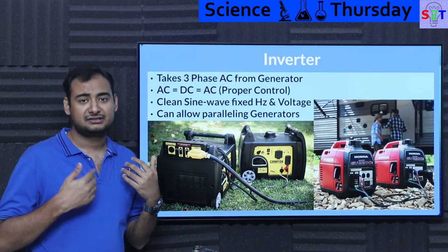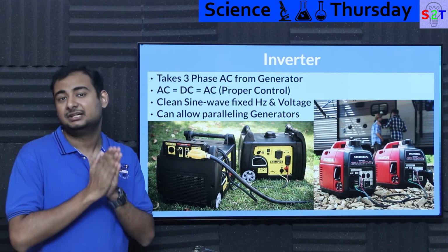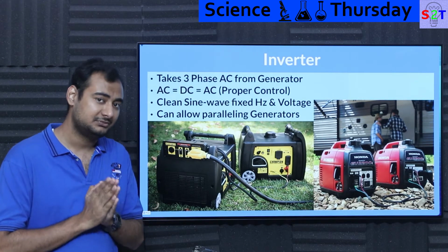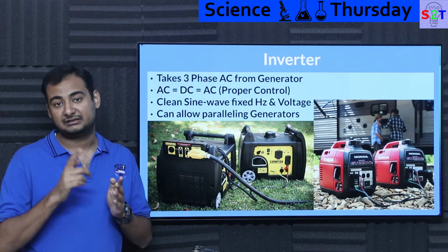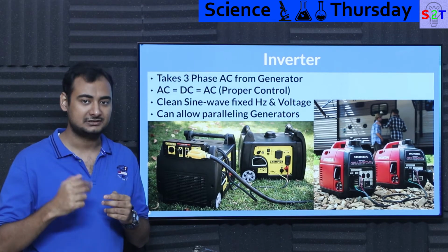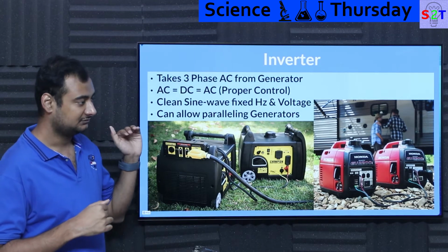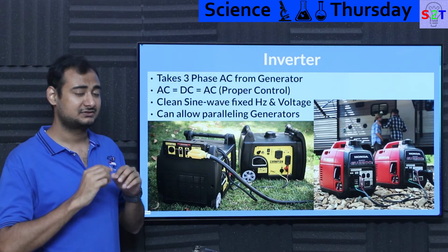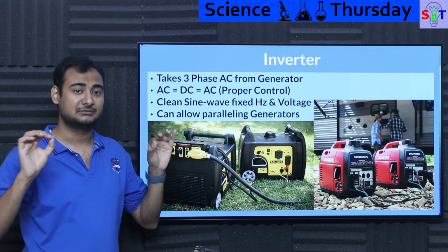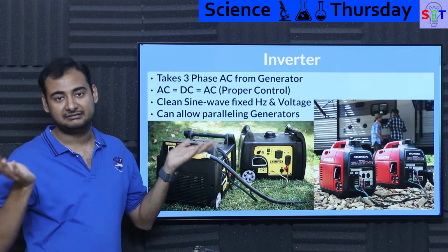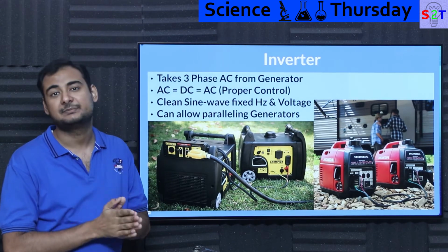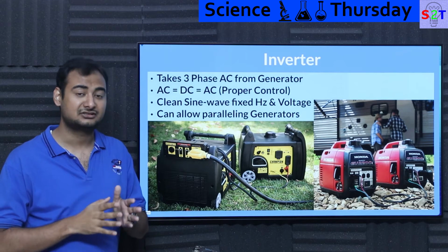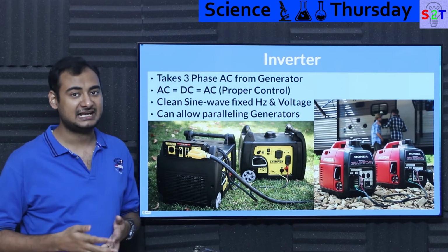Well, even though the generator output will be one phase, if you have three-phase, you will send it through what we call a full bridge rectifier. And each full rectifier generally creates two pulses. So from one phase, you will have two pulses. From three, you can have six pulses. Now 6 pulse is much cleaner compared to 2 pulse. So fundamentally having cleaner DC, you will need less capacitor and less inductor to smooth out the power. So you always want as many phases as possible.